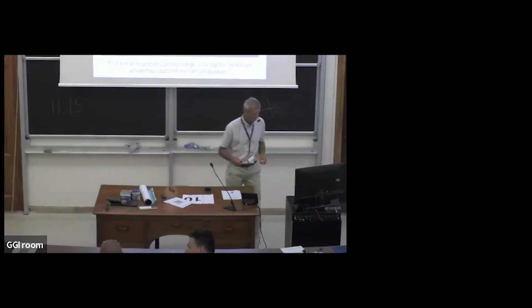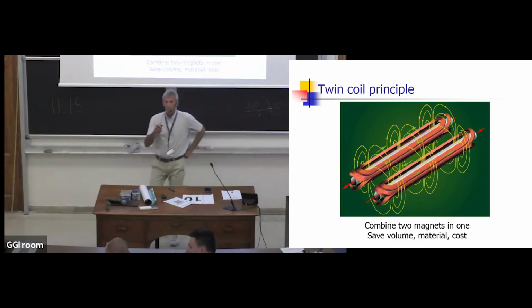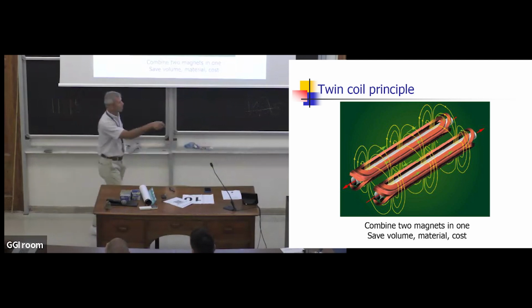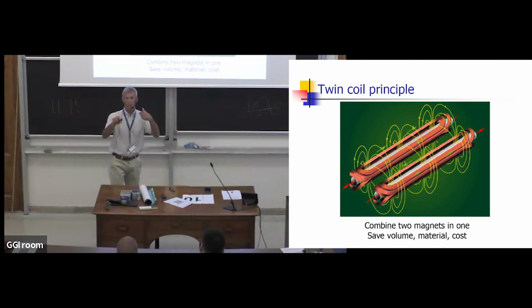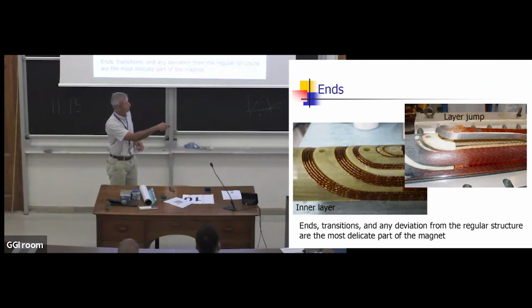In the meantime, I just wanted to show one thing. There was a question about the ends. So what happens in the ends? Because yesterday I was showing just cuts, right? So the cuts are a line here. If this is an LHC dipole with two magnets, positive and negative, protons in opposite direction, that's the ends. That's when you curve the cable, and obviously you have to go outside of the plane because otherwise you have no space for the beam. So that's the end of what we call a cosinus theta magnet. And the way it's done is by winding with these machines, these ends. I hope you can see that, right?